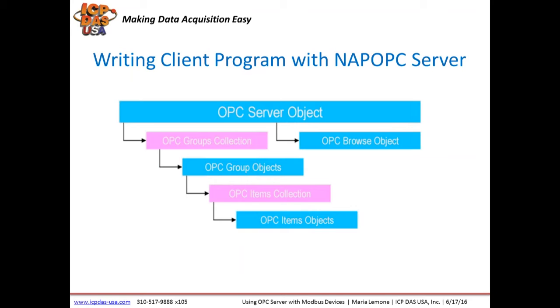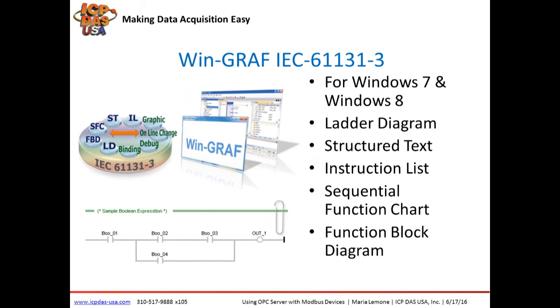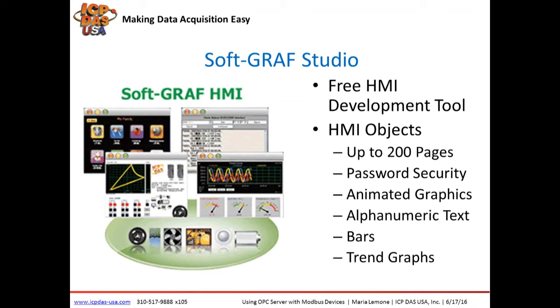We provide a free eLogger software for these types of controllers that run CE.NET 5.0. You can map up gauges, buttons, tanks, and other objects with actual I/O so you can see their status and monitor it with the touchscreen. It's very easy to set up. These PACs can run multiple programs, so you can run eLogger, Indusoft, an IEC 61131 program, a Visual Basic program, and NAPOPC Server all on the same device.